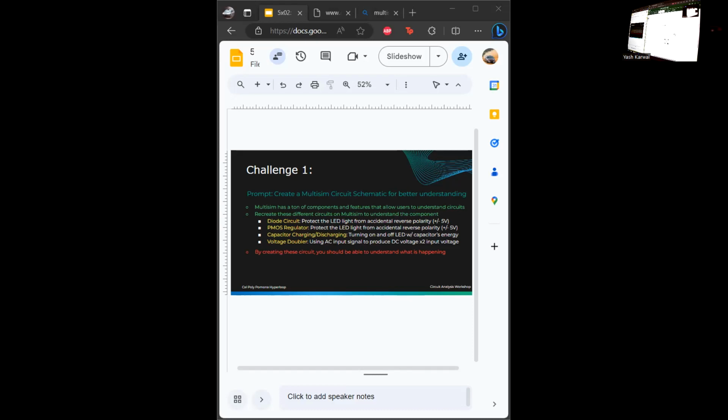Also, you have to note that different colors require different voltage drops. I think yellow is less than red, because red is the most consuming. When you get to the circuit construction workshop, there's a challenge to light up some LEDs with buttons. If you use all red, it won't light up, because there's not enough voltage to supply all those LEDs.